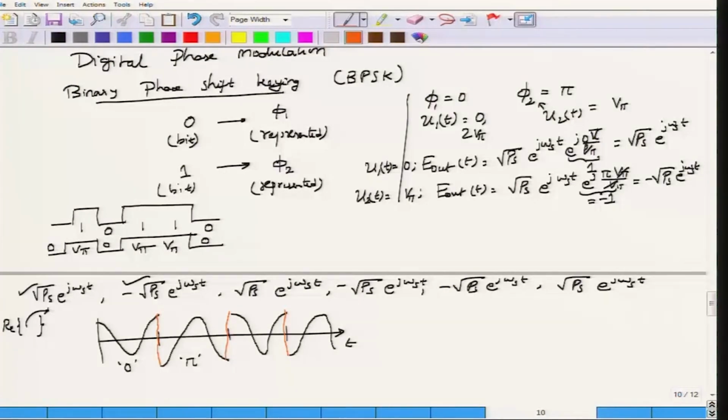So, how can I call this digital modulation? Well, it turns out that what you are interested in is not these amplitude variations, but rather the phase, and when you perform the appropriate phase detection on this waveform, you will be extracting the phases 0, pi, 0, pi, pi, 0, which are then mapped to bits 0, 1, 0, 1, 1 and 0.